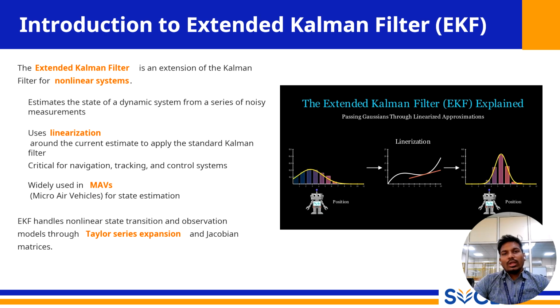At its core, the EKF's purpose is to estimate the state of a dynamic system from a series of noisy measurements. This is precisely the problem we need to solve for our MAVs. We have a dynamic system, the drone, and a series of noisy measurements from its sensors. And we need to produce the best possible estimate of its state, such as its altitude, velocity, and position.